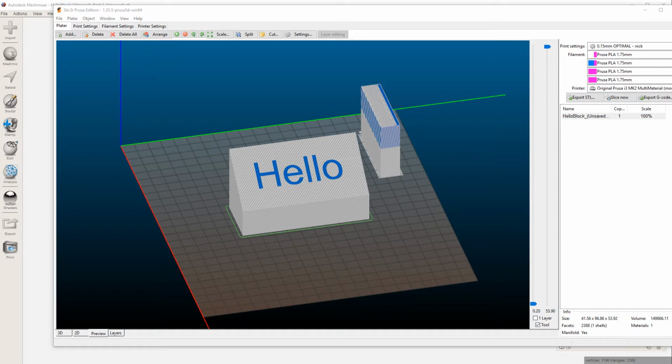Essentially, you just need a 3D model to be next to a 3D model in 3D space absolutely perfectly, but without overlapping. Because if they overlap, you can certainly export a file that has that, but then it's up to your slicer to figure out how to fix that overlap. Sometimes the slicer will do it just great, and sometimes it won't. I really wouldn't trust slicers to do a lot of repair. You should just repair that inside of other tools, or just have good output to start off with.